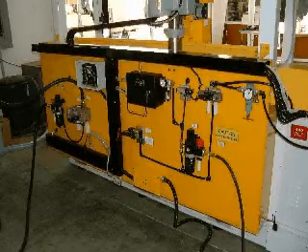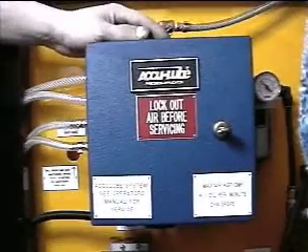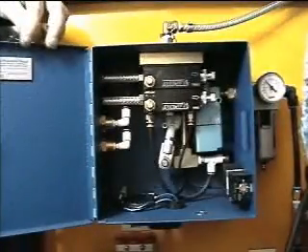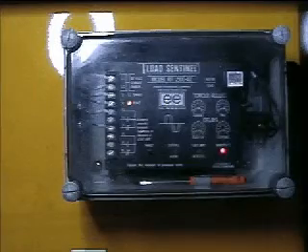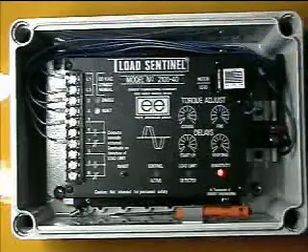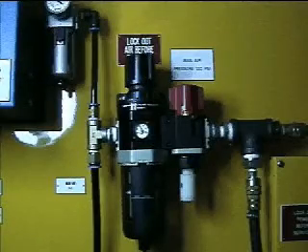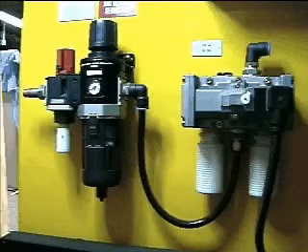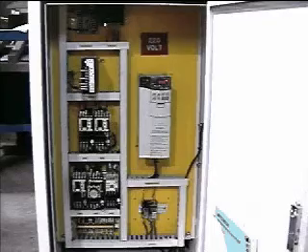At the rear of the machine, components and pneumatic controls are mounted. The AccuLube system is provided to extend drill tool life and to reduce the stress on the parts. The load sentinel is a torque monitor that is used to indicate the drill touch point on the part. CKD pneumatic controls are standard. We can build to the customer request. A separate pneumatic system is used for the chip evacuation system, providing machine flexibility.